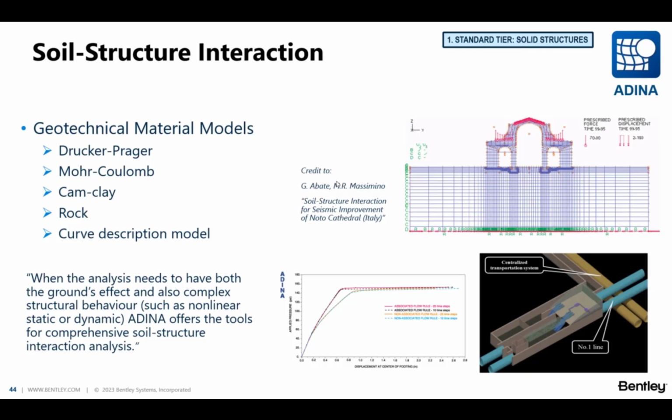In addition to those material models, we have the possibility to use compression-only springs for static and dynamic, and also to use springs and assign nonlinear P-Y curves if we have piled foundations.